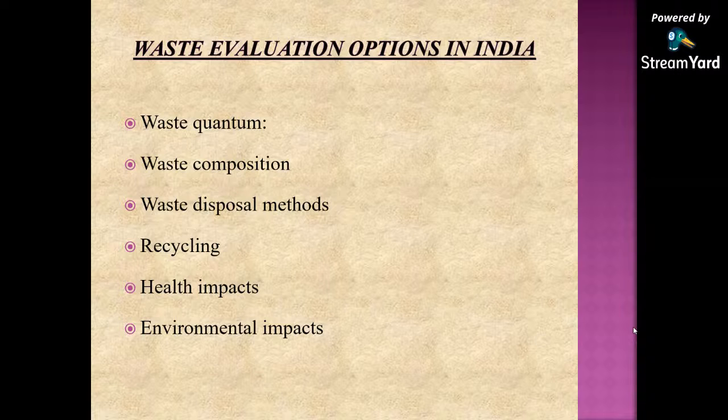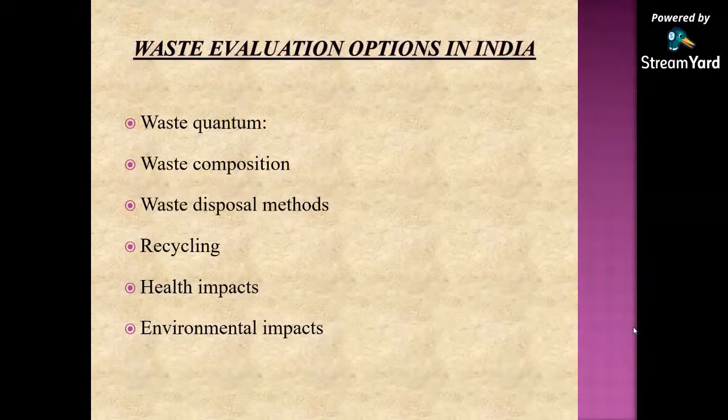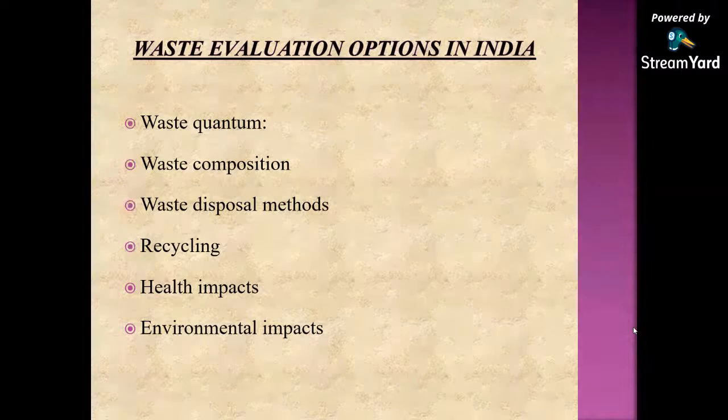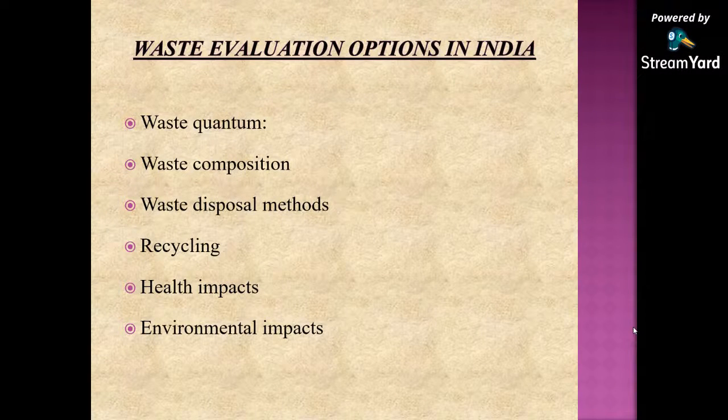The garbage in Indian cities is estimated to contain about 45 to 75% biodegradable waste and 50 to 55% moisture, then 35 to 45% fruits, vegetables, and food biomass, then 8 to 15% of non-organic materials like plastic, metals, glass, stone, etc. The refuse from Indian cities also contains high organic and low combustible matter, as the studies carried out in 6 cities indicate.